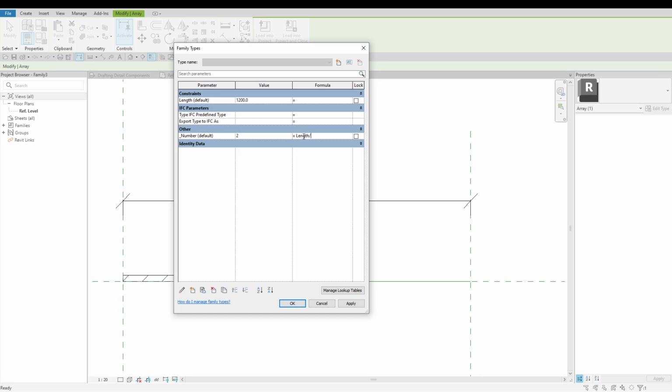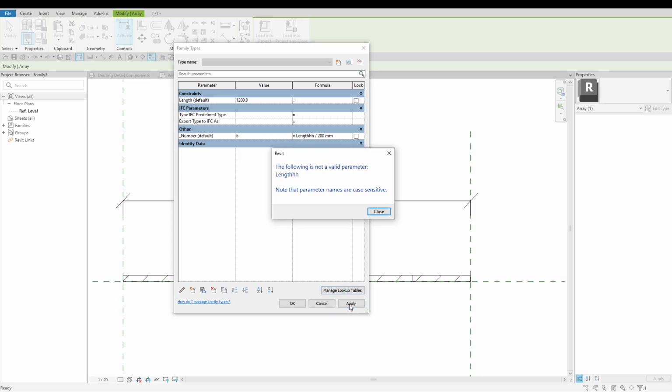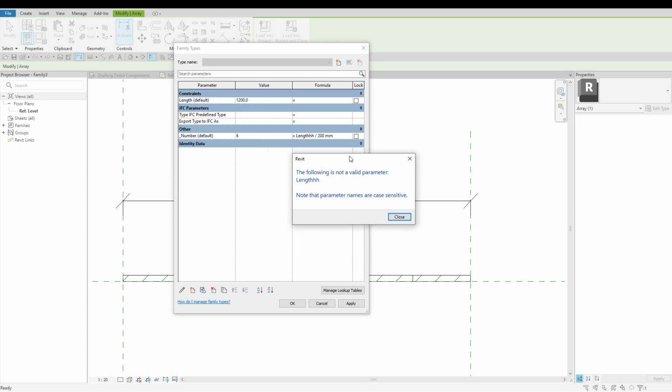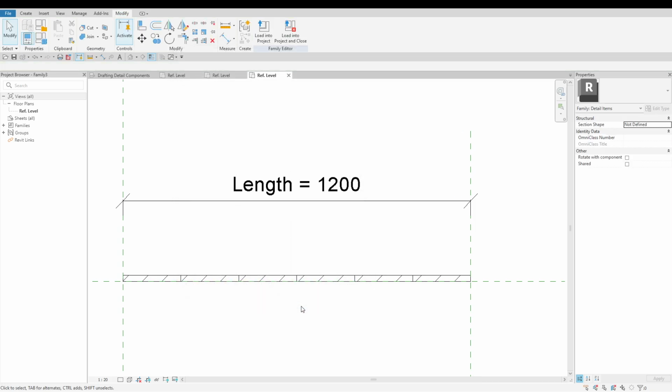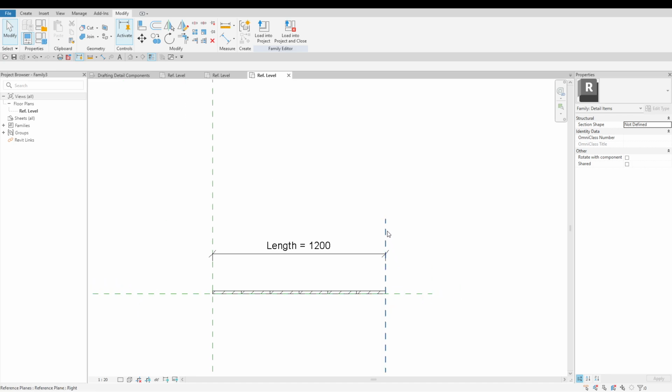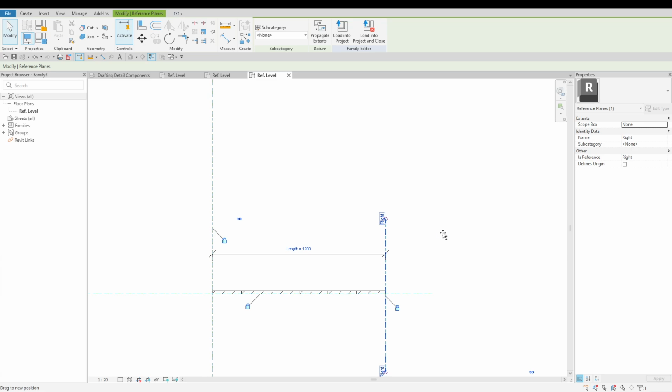It is very important to avoid grammar and syntax mistakes when writing formulas for parameters in Revit. Revit is strict about formula structure, and even a small error can cause the formula to fail or produce incorrect results. A minor mistake can render the entire formula invalid. In such cases, Revit will either display a warning or prevent the formula from being saved. Before loading the new line-based detail component into the project, make sure to check it in the Family Editor first.